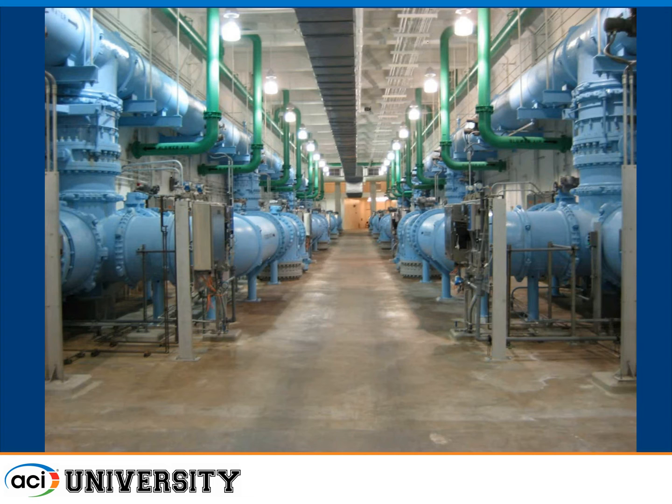This is about a 30, 35 foot high wall that's intended to be entirely liquid tight through the service life of the structure. And there's no pumps here, but you may actually have a pump gallery that's right next to your particular structure that you're getting dynamics. We do wastewater treatment where there's treatment equipment that has large torques that happen on the structures. So very, very different than the types of things that you see in a building structure.